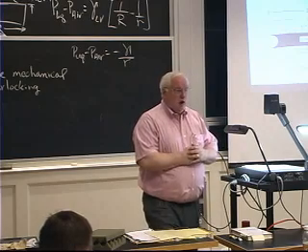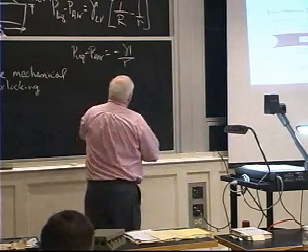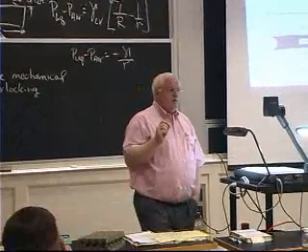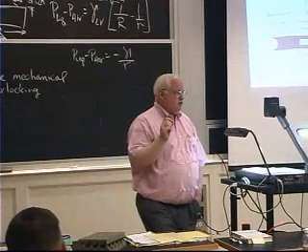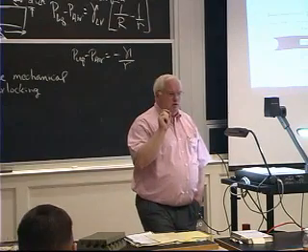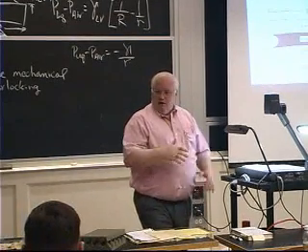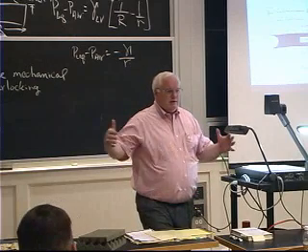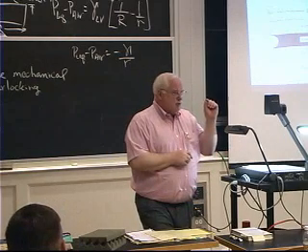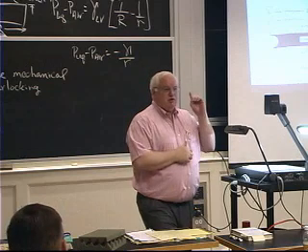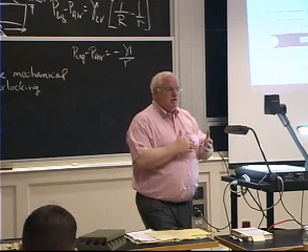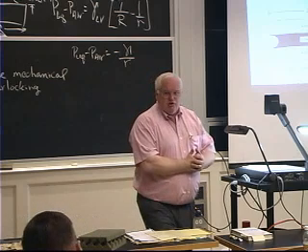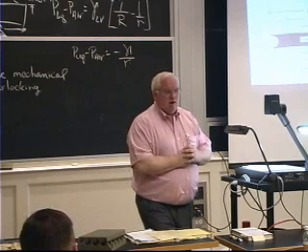measuring things. However, has anyone ever seen a ball bearing micrometer? The types of micrometers they use to measure the balls on precision ball bearings. It's kept in an air-conditioned room, plus or minus 2 degrees Fahrenheit, and it's the size of a small lathe to measure something that might be 1/10 of an inch in diameter. But it measures it to 50 millionths. Because if you start thinking about coefficients of thermal expansion, 5 degrees Fahrenheit will change your dimensions by your tolerance.